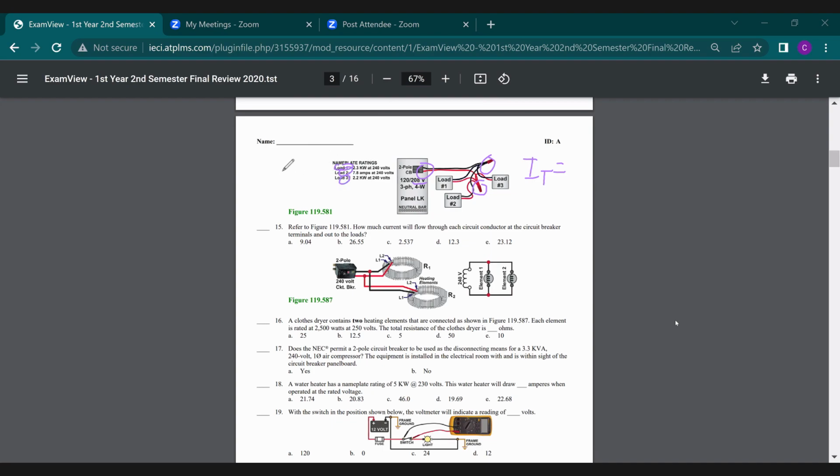For my kilowatt sets, it's going to be E squared divided by P, just standard watts, to equal R. And then for the amps, it's E divided by I equals R. Plug those in, get me a load 1, 2, 3 resistance, and then we'll go from there.